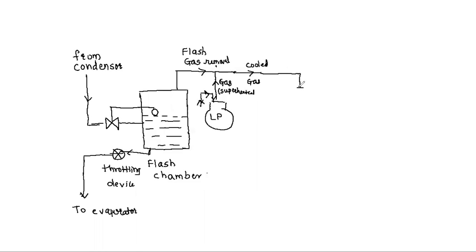If I want to represent this on a pressure enthalpy diagram, this is now an interesting diagram. Look at what is happening. Suppose we again use the same nomenclature, this is 1, this is 2. After mixing, this is 3, and after compression in the high pressure compressor, it is 4. So this would look somewhat like this. This is a pressure line. The vertical is the pressure, the horizontal is the enthalpy, and this is the vapor dome.